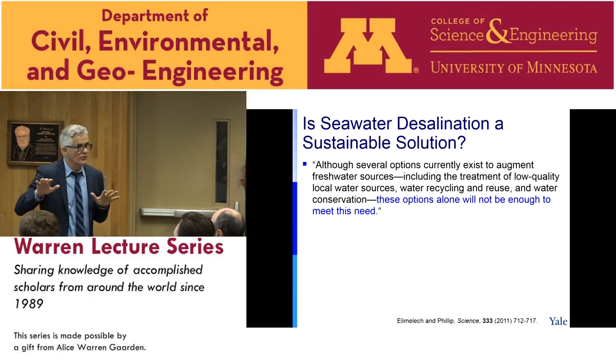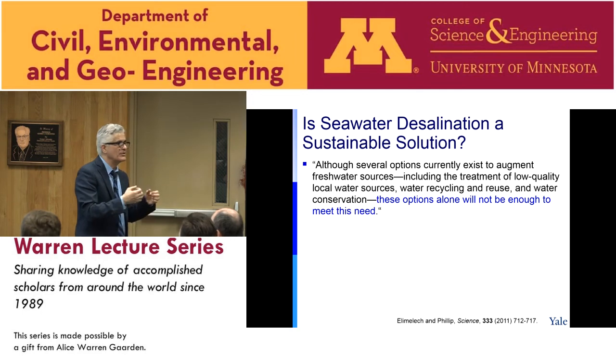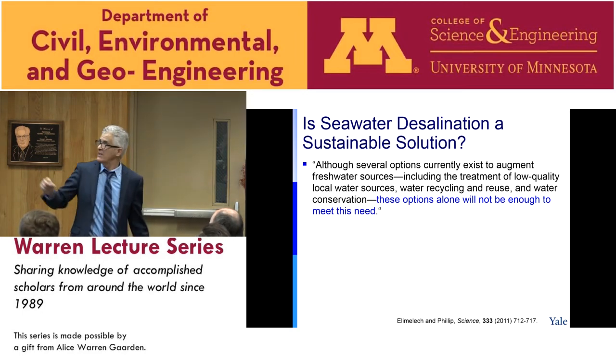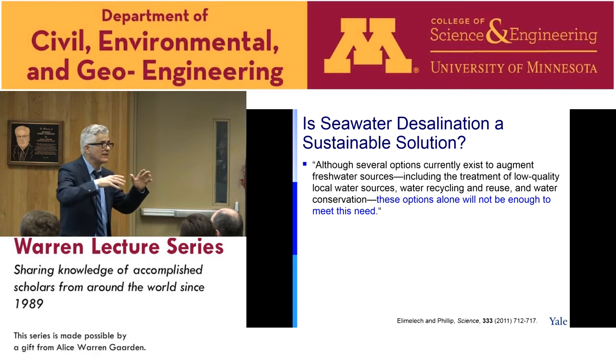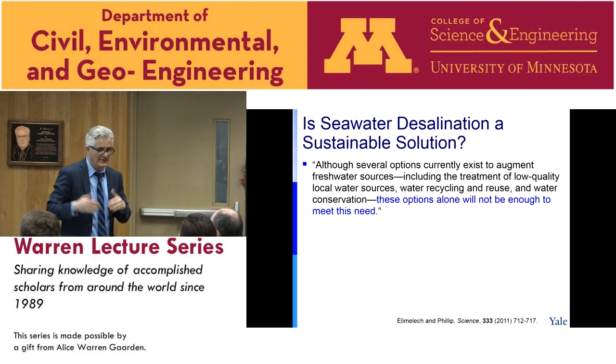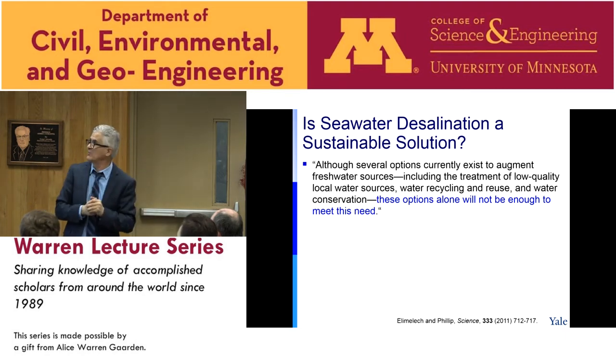And there is a big push in many countries, and especially in California, to reuse wastewater and have it for direct potable use, that you just treat the wastewater and immediately get it to the distribution system. And roughly, I did not mention it, the total energy of this reuse process for wastewater is about 1 kilowatt hour per cubic meter, much less than the desalination. So we need to push it. But even if you do it, it's still not enough. We still need more water worldwide.